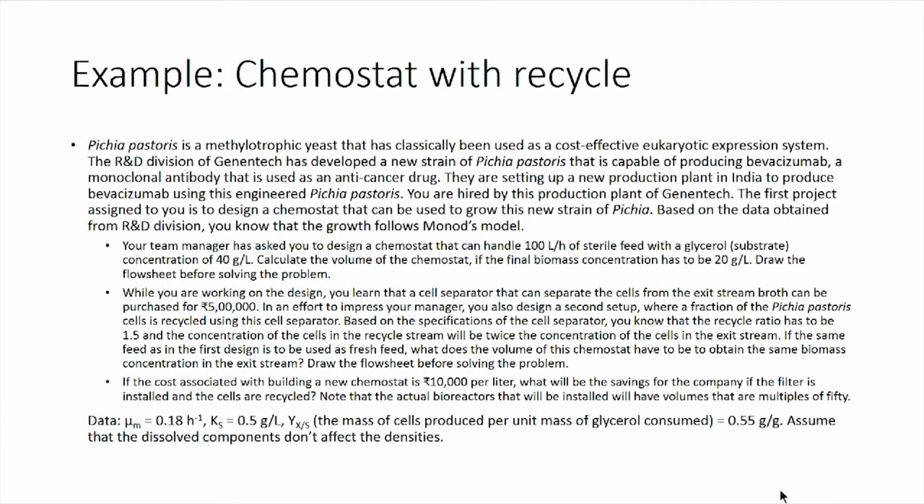Data given is μm equals 0.18 per hour, Ks is 0.5 grams per liter and Yxs is 0.55 grams per gram. So, you can assume that the dissolved components do not affect the densities. Now that all the information is available to you in the problem, let us first start with drawing the flow sheet. For the first system, it is quite simple.